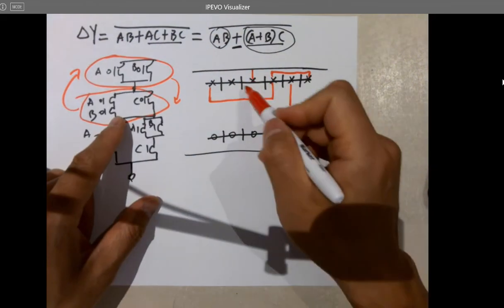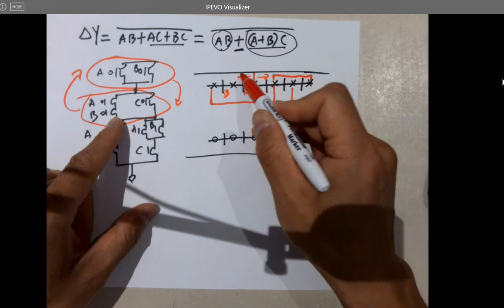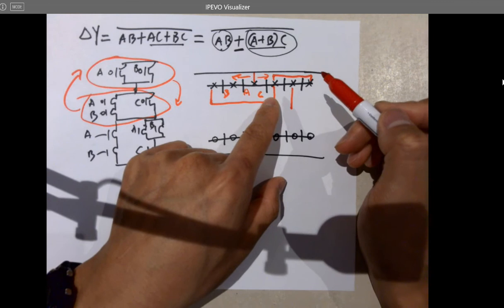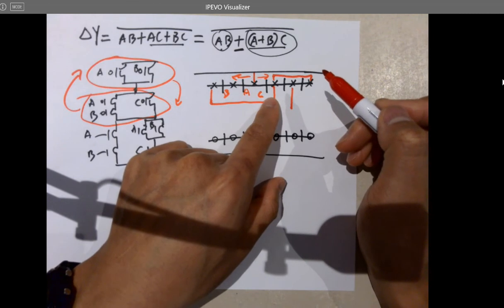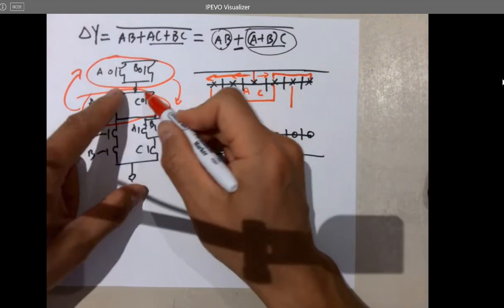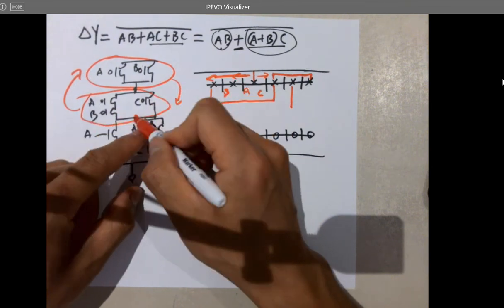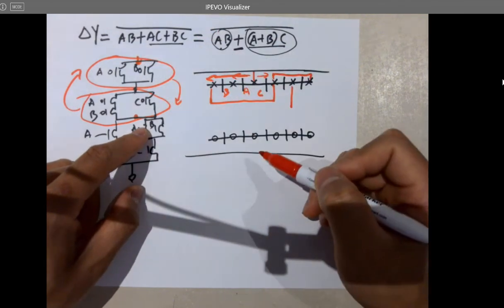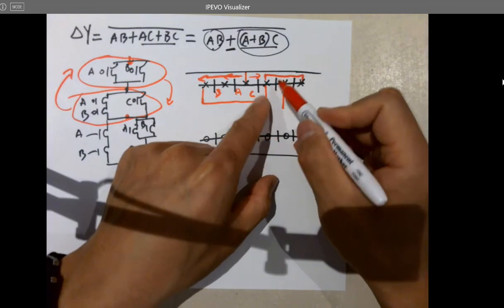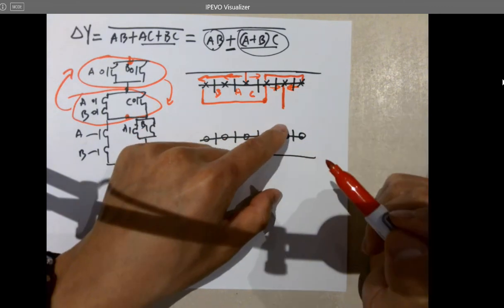So starting from the top, I got A, B in series, and in parallel with this guy. So this guy will be C, right? And because that's one branch, that's another branch, so that's the output of these two branches. And now remember this is on the top, so the output here will be fed into here. And you need the two parallel PMOSes. So that's the merged point. And that's the output. Is that correct?